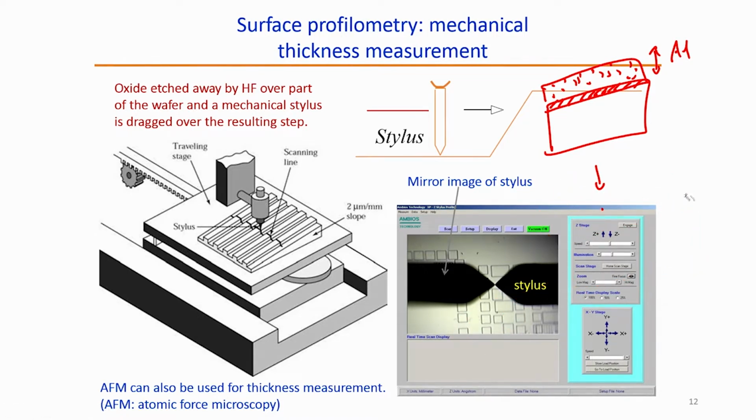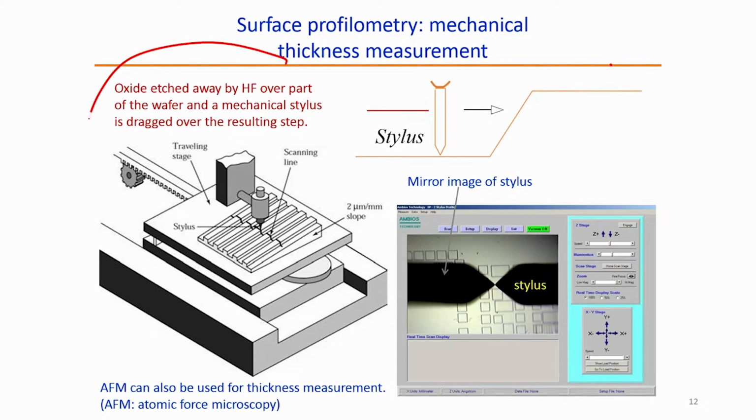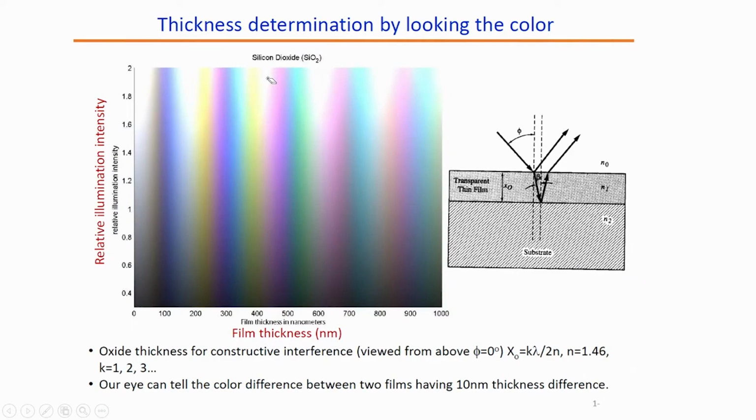Here you can understand the thickness of any material with the stylus profilometer. It has a diamond tip, which makes it easier to use, right. Here they have shown that you can use HF for etching silicon dioxide. In the first example that I took, for aluminum you can use an aluminum etchant to etch the aluminum. We will be looking at this in detail.